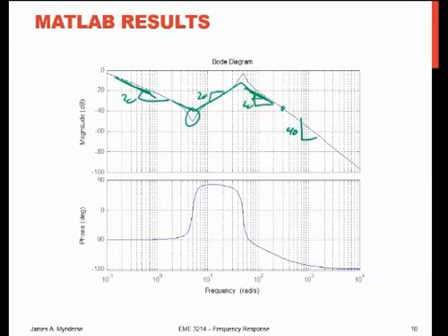And the phase started at minus 90. We hit that complex 0. It started to head up to 180 degrees from minus 90 to plus 90. Doesn't quite get there because I have two things. I have this pole and that pole over here. That pole, it's not a pole, I circled my thing. Those two poles happening, and you can see it kind of starts to roll off there, hits the next complex pole, jumps down, and then keeps rolling off into infinity and beyond. So that's how the drawing looks in MATLAB.